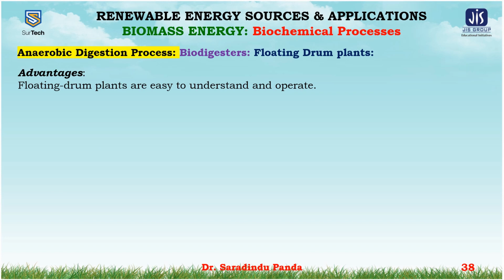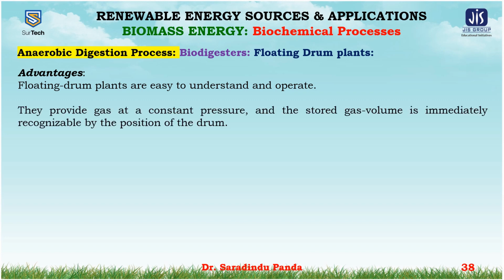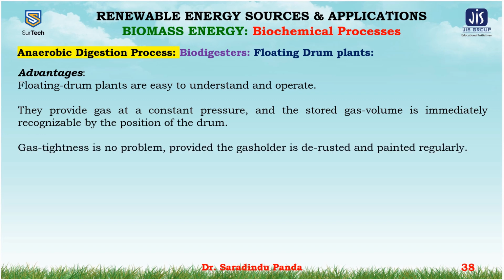The advantages of the floating drum plants. Floating drum plants are easy to understand and operate. They provide gas at a constant pressure, and the stored gas volume is immediately recognizable by the position of the drum. Gas tightness is no problem provided the gas holder is derusted and painted regularly.